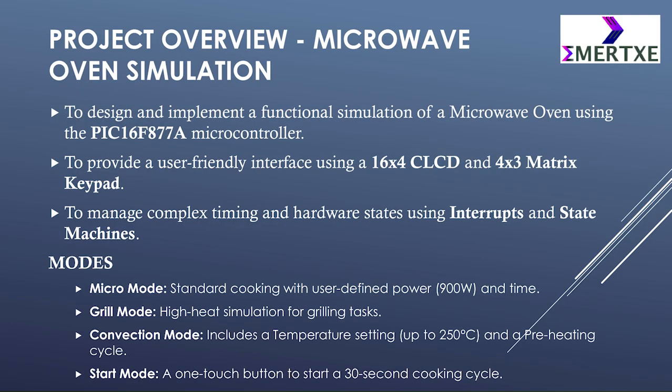Let's discuss the core objective of our project. It was to create a reliable simulation of a microwave oven using the PIC16F877A microcontroller. We didn't want just to blink the LEDs. We wanted to replicate the actual user experience of kitchen appliances with a user-friendly interface using a 16x4 CLCD display and a 4x3 matrix keypad. This involved managing multiple cooking modes, handling users' input for time and temperature, and ensuring the safety and accuracy of